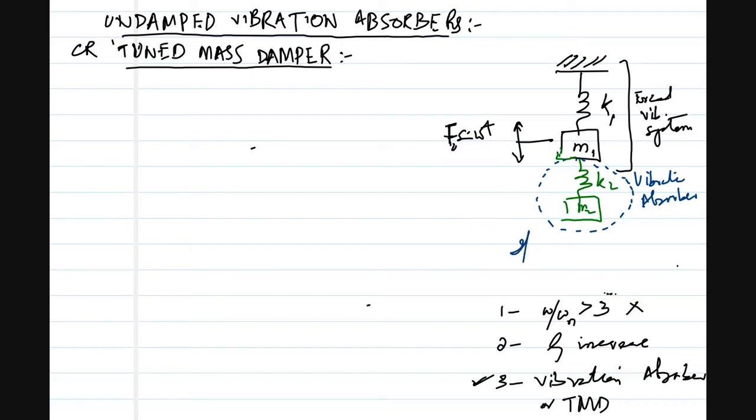that if omega, which is the forcing frequency of the force coming from any source, becomes equal to omega 22, which is the individual natural frequency of the absorber mass and spring, then, for example, let's say its vibration is x1 of t, and this is x2 of t, like we are doing in the normal mode analysis.